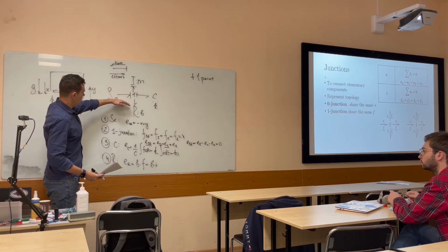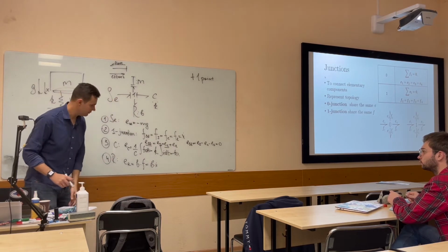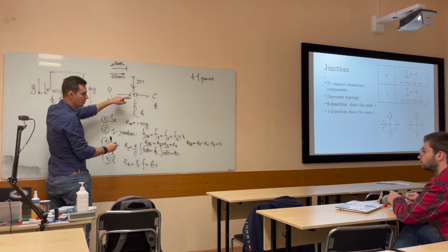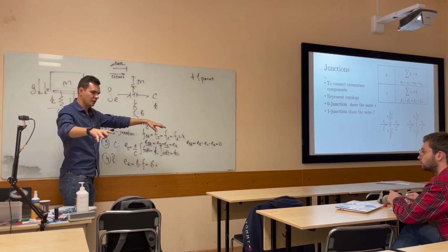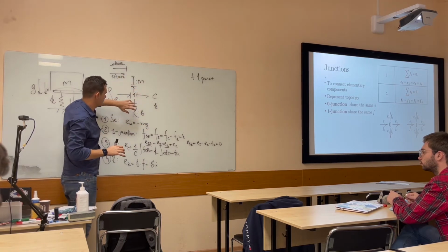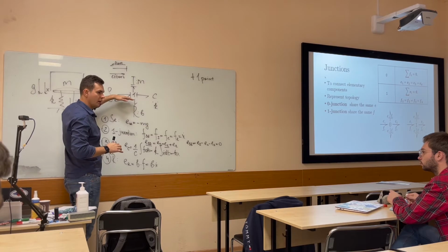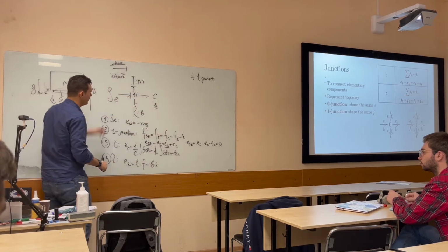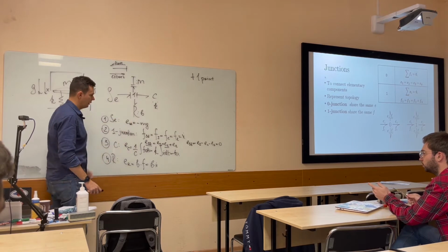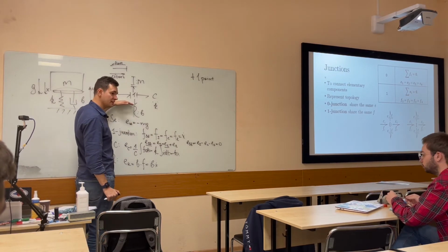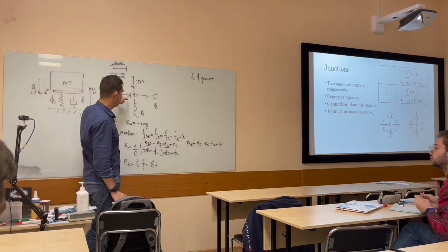You can see it in our graph. So we send all the power to this one junction, and then all the power goes to all the bodies. So it's like the power has been distributed among all the components. So we take signs from the direction of power flow.